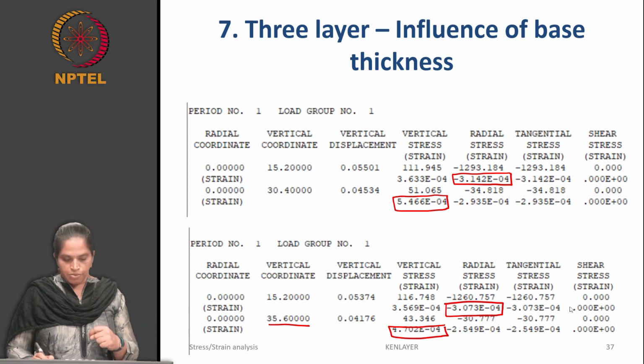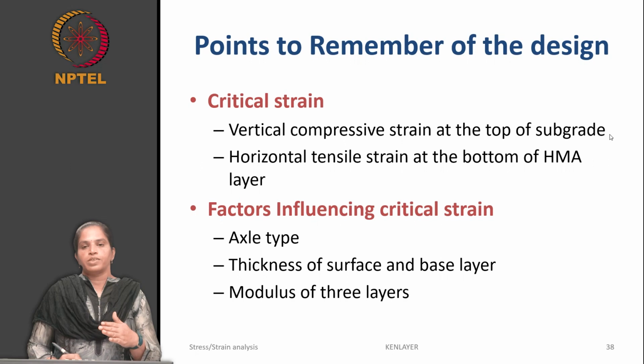We have solved 2-layered system and 3-layered system using KENLAYER software and understood how the thickness of different layers, modulus of different layers, or different axle configuration influences stresses and strain at critical locations.